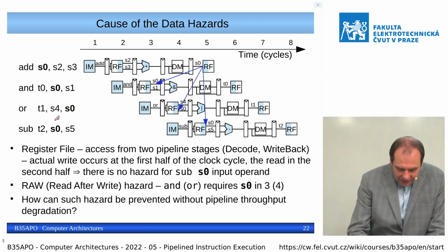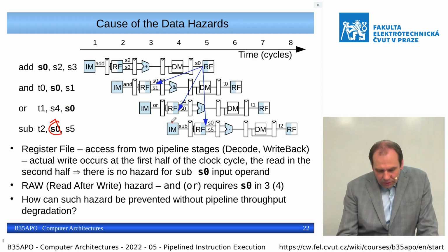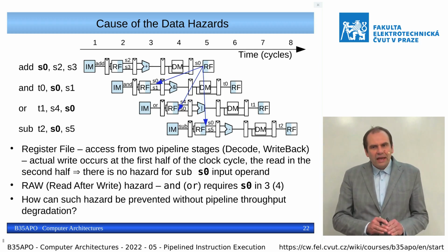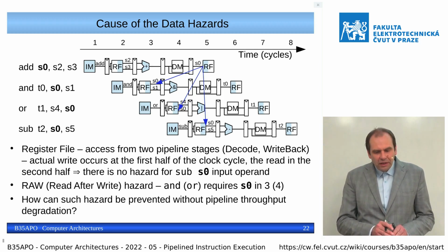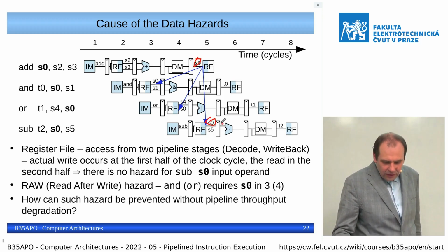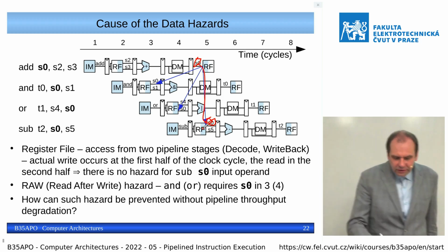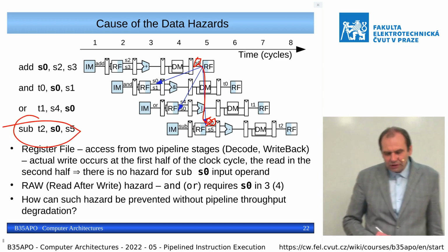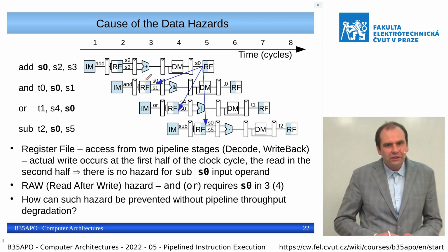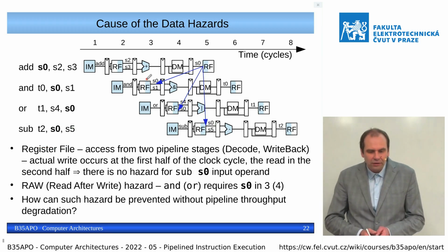So we read some previous value which is incorrect. For the last instruction, it is fetched and decoded in the 5th clock cycle, and we have defined that our register file is able to accept the write. If we write to a register which corresponds to one of the registers being read, then the value is propagated to the output, so that this 4th instruction, subtraction, is executed correctly. But those two previous instructions are executed incorrectly with incorrect data.